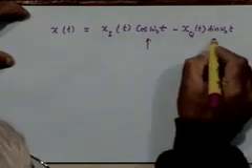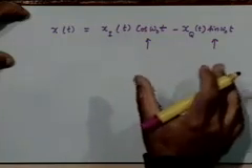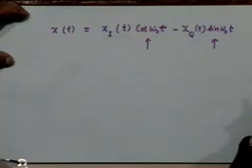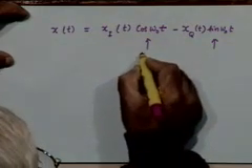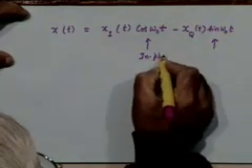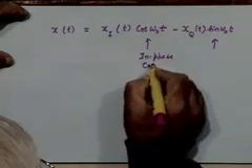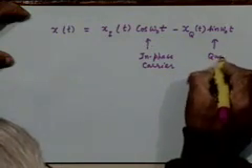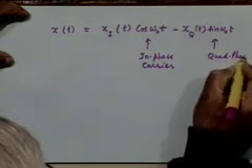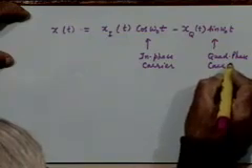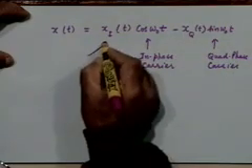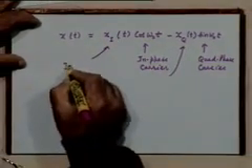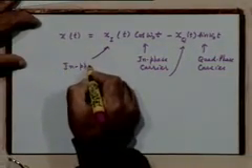These two carriers are quadrature components of the carrier e to the power j2 pi f naught t. They are the real and imaginary parts. It's just terminology. We call this an in-phase carrier and this a quadrature phase carrier, and these two are the in-phase and quadrature phase components of x(t).